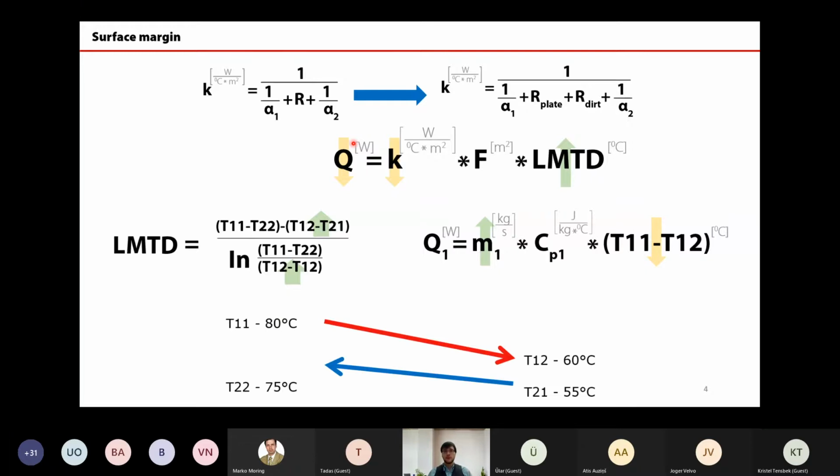And in the most general way, if we make a temperature graph for some application, let's say in Central Europe, where we have somewhat lower supply temperatures, if we designed our system for 80 to 60 degrees on the primary side and our heat exchanger starts getting dirty, that means my primary outlet will start increasing, maybe to 65 degrees, together with the increase of the mass flow. Both these things, increasing primary return and increasing mass flow rate, are actually harming the efficiency of the district heating setup in general.